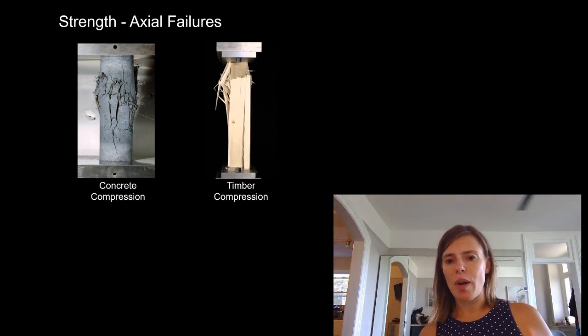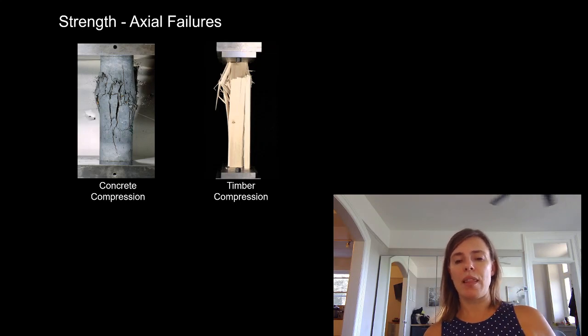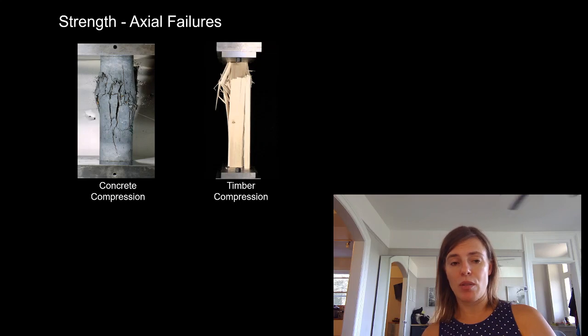Concrete's kind of interesting because we don't know how strong it is until after we build it. Where steel, we know in the plant how strong it is. And wood, we have ways to gauge what the strength is before we build with it. But concrete, we have to be pretty darn certain we know how strong it's going to be when we cast that concrete. Because if we're wrong and it's not strong enough, we have to do a bunch of work.